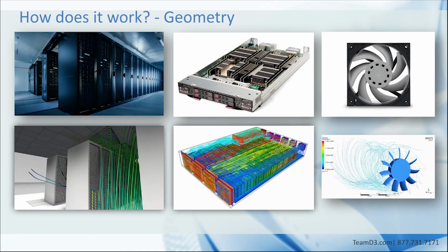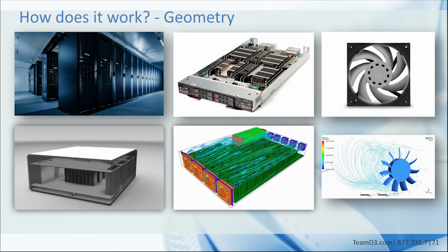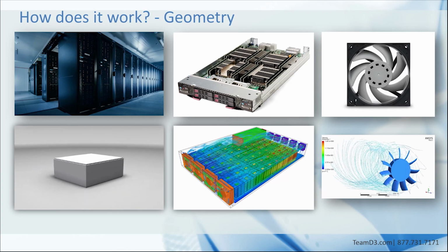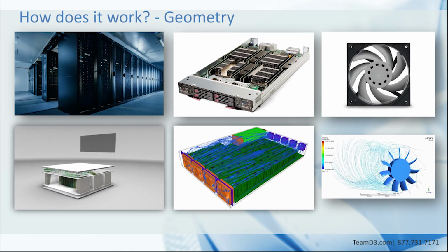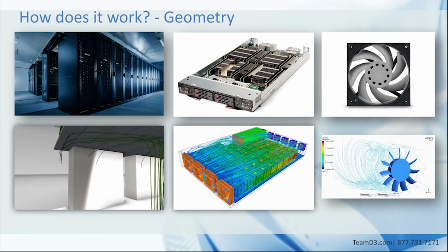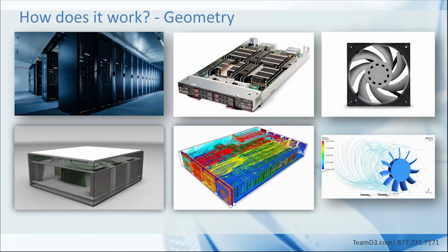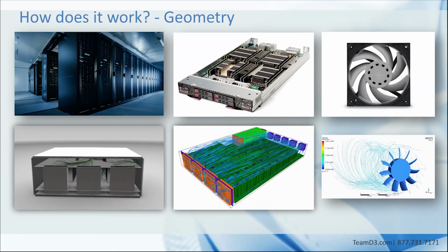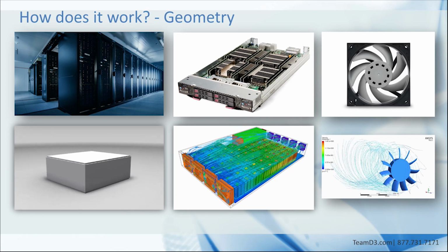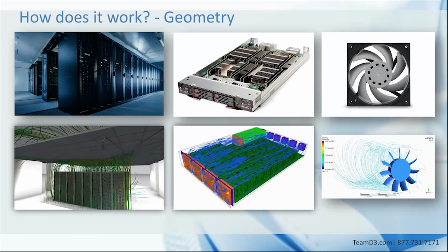For example, if we wanted to study the flow and thermal characteristics of a data center, we absolutely can, and this is a common CFD application. However, our room scale model will not include the screws holding up our light fixtures. It won't include the heatsink fins in our blade server. It won't model the server cooling fans spinning and the turbulent structures they generate. Instead, we'll make some assumptions about how much heat the entire server rack emits and the average velocity of its exhausted cooling air. This would be enough information for us to make decisions about our server layout and the location and power of its cooling units.